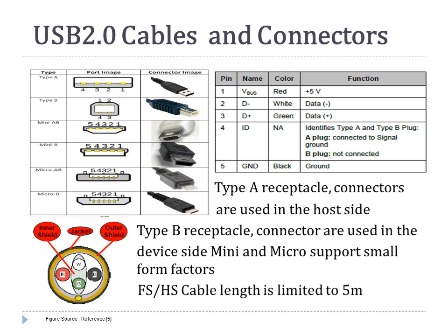A little bit of detail on the USB cables and connectors. The type A connectors and receptacles are used on the host side, and the type B connectors and receptacles are used on the device side. With more and more penetration of USB into devices of smaller form factors, other smaller receptacles and connectors like mini and micro USB were developed. And as you are seeing, most of the cell phones currently use a micro USB connector, and I'm sure you're familiar with it. The USB uses a twisted pair for its data lines.